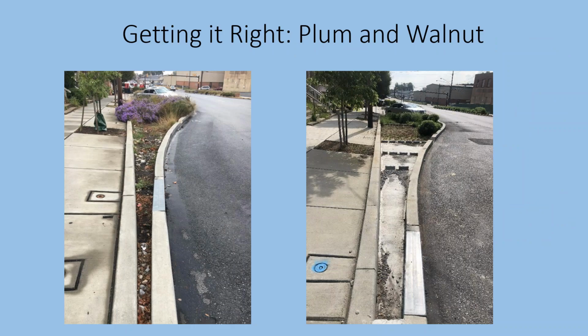And you can see the difference in this slide and in the next in terms of what a difference those forebays made. So in the left picture here, you can see that there's a lot of sparse weeds growing. You can see some of the cobbles poking out. It's not a really effective, or for that matter, pretty piece of this particular rain garden. On the right, you can see it retrofit with the forebay.